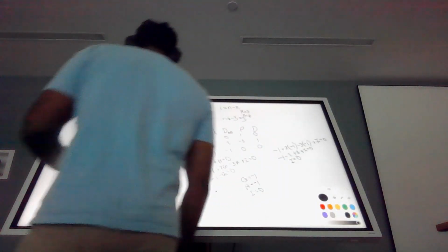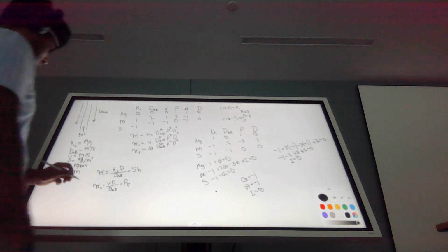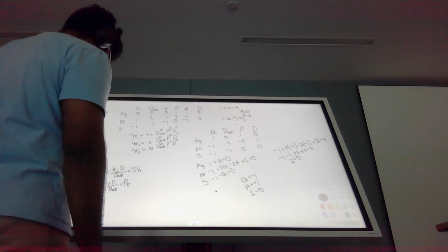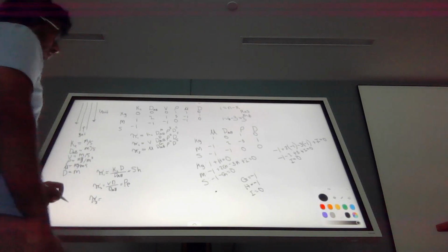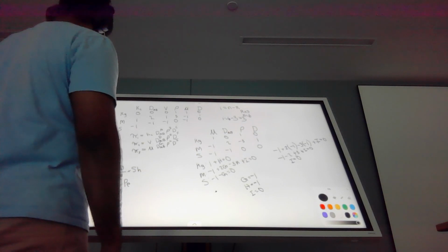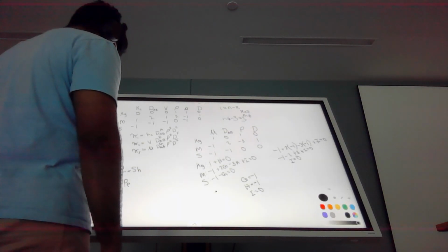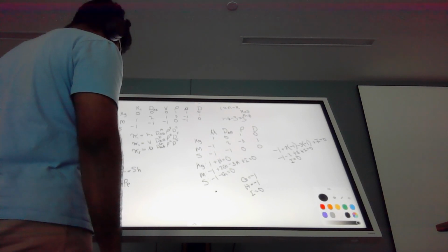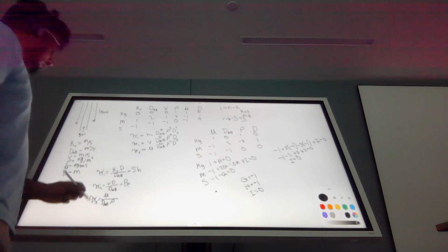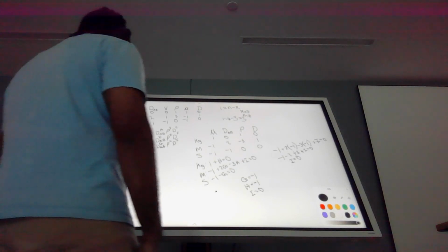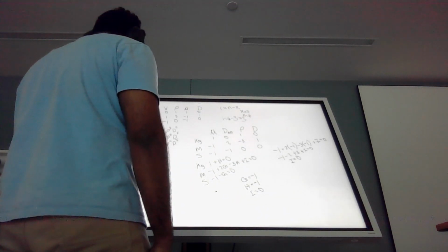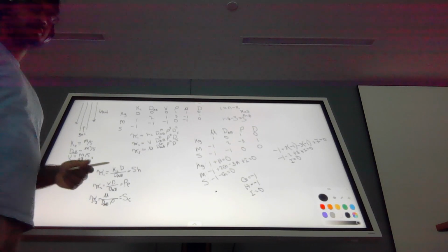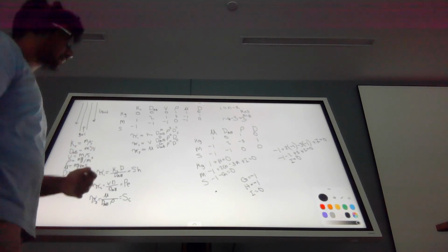So G, H, and I is equal to 0. Then now we go here and write our pi 3 equation, which is going to be our third dimensionless group. And that's going to be mu, DAB and then density. And this is going to be our Schmidt number. So pi 3 equals the viscosity divided by the mass diffusivity times the density.